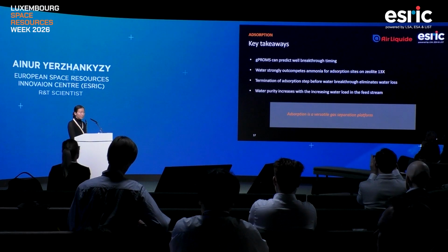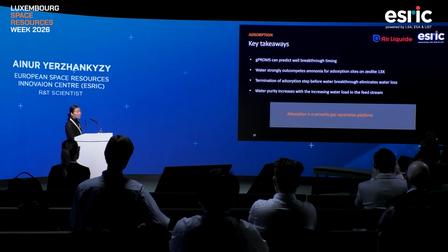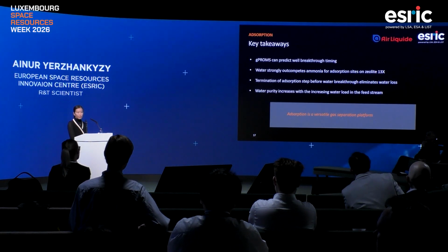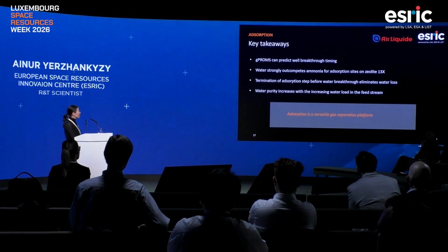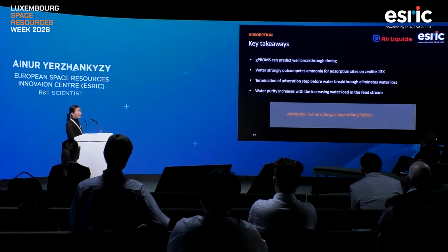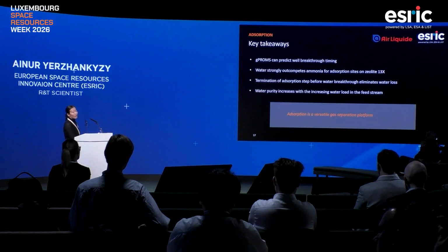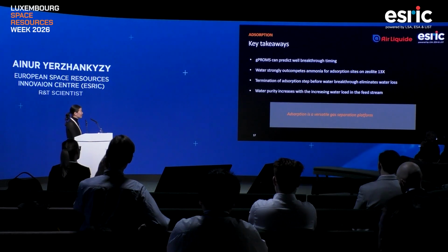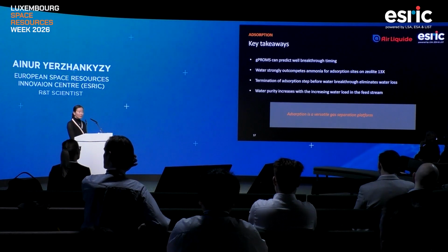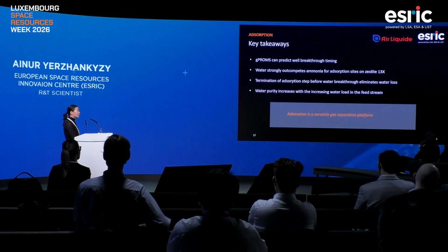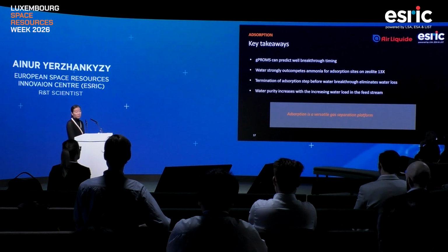And with that, I wanted to say that gPROMS, so far, we observed that it works well in predicting the time of the breakthrough. However, we still need to do more experiments to adjust the mass transfer coefficients, and then optimize the purity levels of our product. And what I wanted to highlight again is that adsorption is a versatile process. So if you see this application might be useful in one of your processes, just reach out to me. I'll be happy to have a chat.